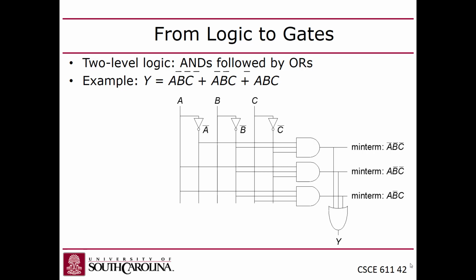You guys with me? The problem is if you have 2 gates that are both connected to the same output, if you short the outputs of 2 gates together, and if one gate tries to pull up, like tries to output a 1, and the other gate tries to output a 0, you end up creating a low impedance path between power and ground, because you create a connection where you've got one net, one signal, one wire that is both connected through to the VDD rail through one gate and to the ground rail on another gate, right?